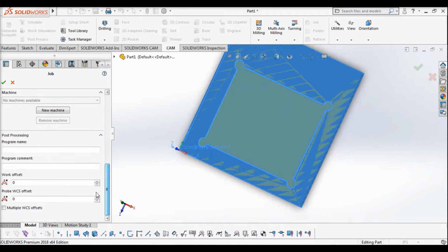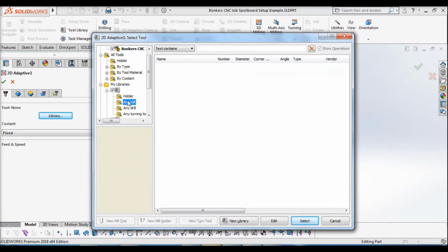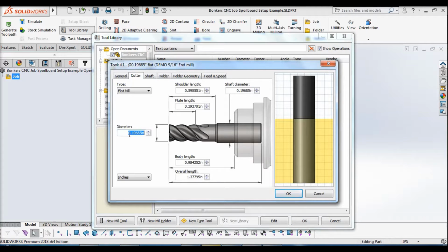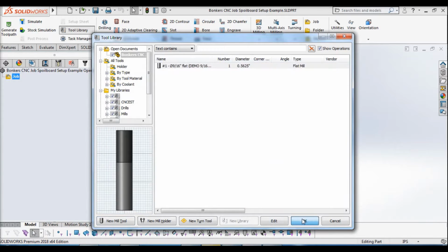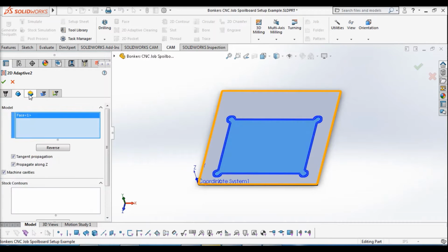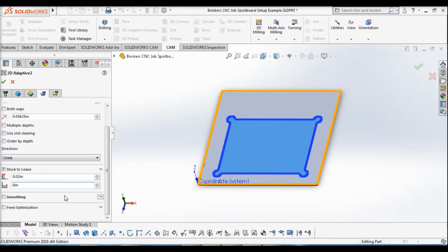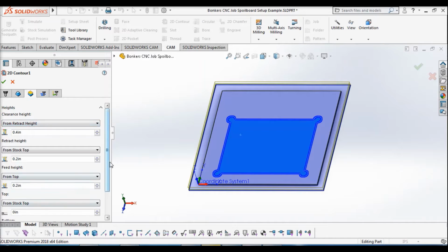So you can see I'm putting a coordinate system in the bottom left-hand corner, and that corresponds to that MDF. But the important thing here is that that pocket gives me another lower left-hand corner to register my piece on, and a very flat plane for my Corian to sit on. So I can keep that coordinate system from the top of the MDF, but when I put my piece into that little pocket, assuming I've measured the thickness, length and width of my piece correctly, I'm going to be able to very accurately locate onto the stock.